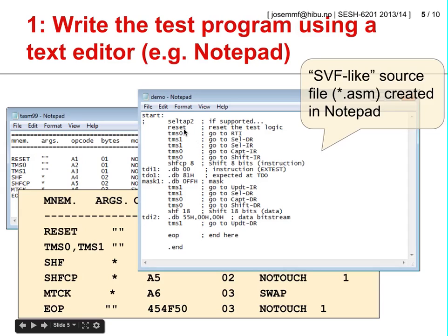Please keep in mind that you should revisit the boundary scan slides in order to understand this example, and particularly you shall bear in mind what is the test access port controller state transition diagram, since that is what explains why we need to execute this sequence of TMS commands. Anyway, we will start by resetting the test logic, and so this first command will bring every test access port controller in each device to the test logic reset state.